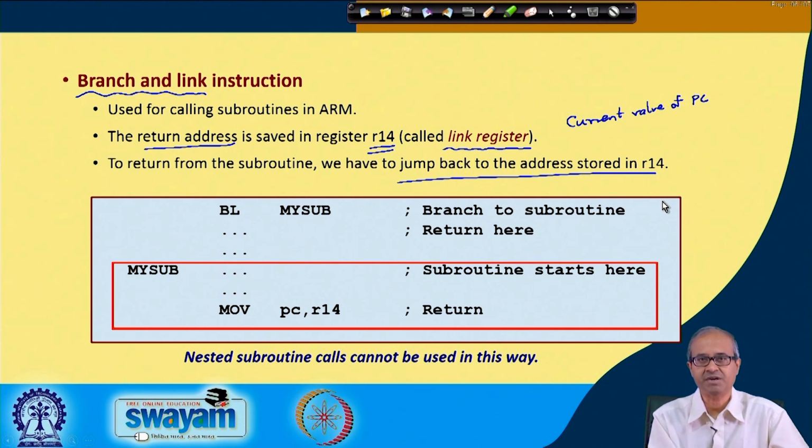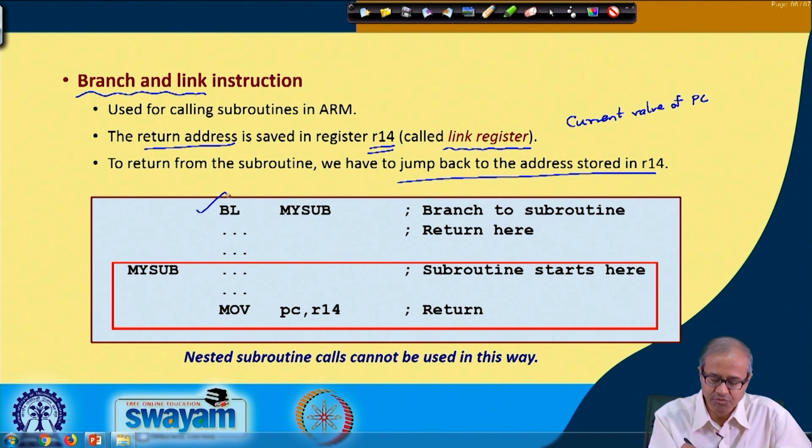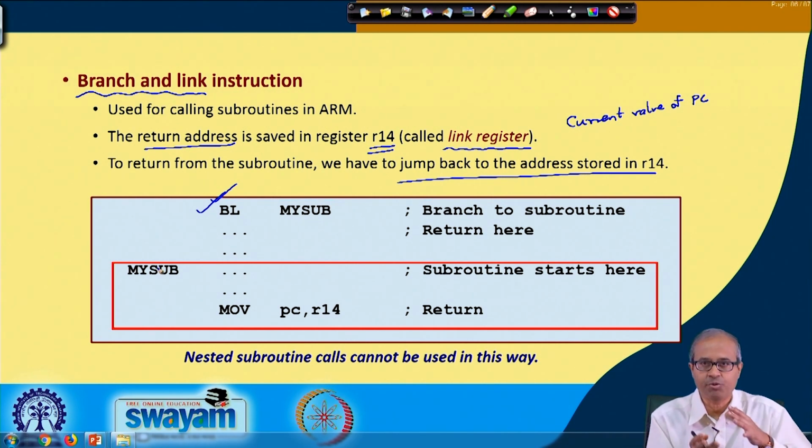Let us take a simple example here. A very small code segment is shown. Suppose this is a program. Somewhere in the program you have given a subroutine call instruction, branch and link, BL is the mnemonic for that, and this is the subroutine you are calling. Let us say my sub is the label of the subroutine, and this red box indicates the body of the subroutine.